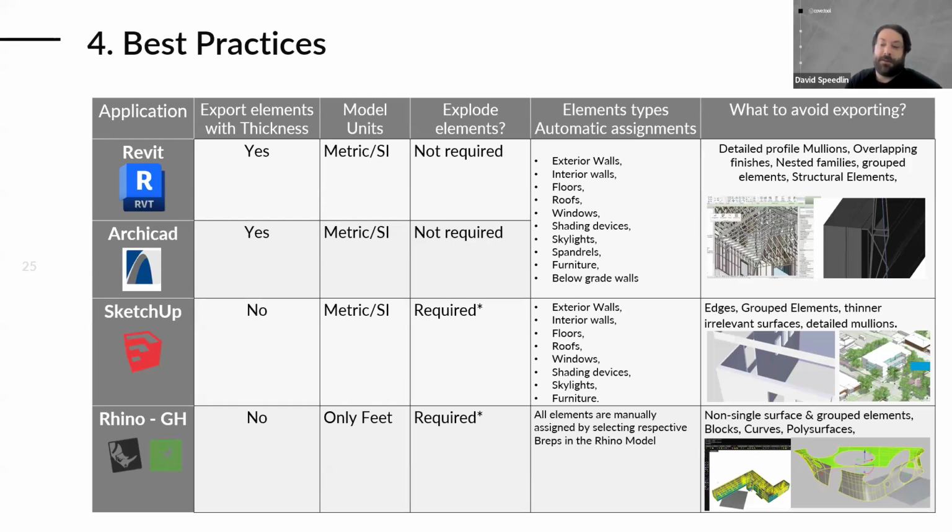Some of the best practice in SketchUp that I see a lot is when you run the plugin and then you come back and make some adjustments, you need to make sure that all of your edge line tags are set to untagged.